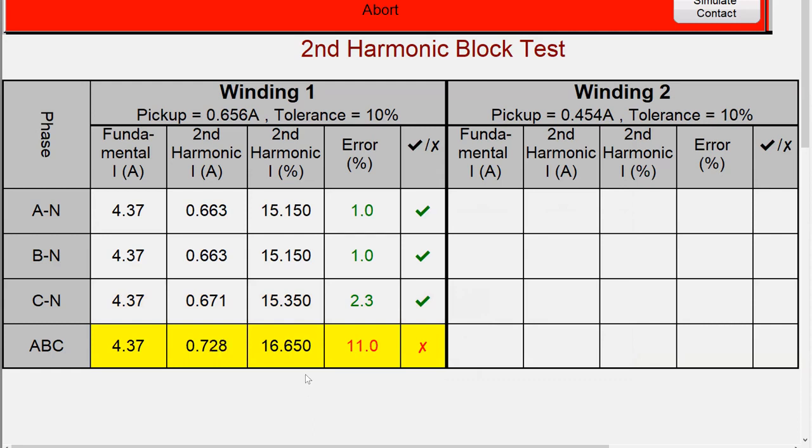So here I have the three-phase test that is going on, and it's the same kind of calculation. Now it's going to inject 3 currents on all the phases, right, of 60 hertz, and 3 more currents on the same phases at 120 hertz. So the SMRT units have the capability to inject more current waveforms just utilizing single current channel. It can in fact inject up to 4 different frequency waveforms utilizing the same channel.